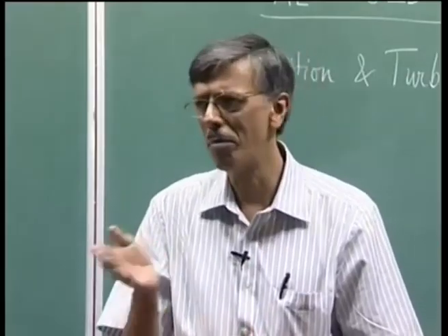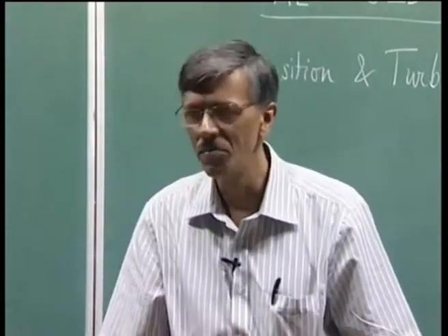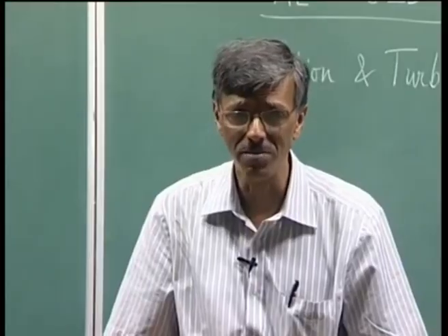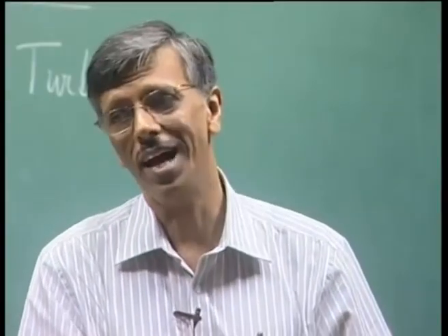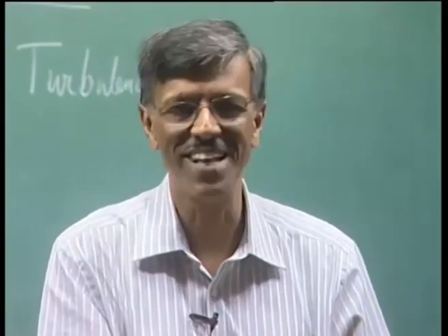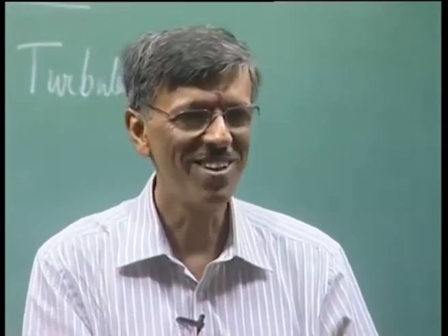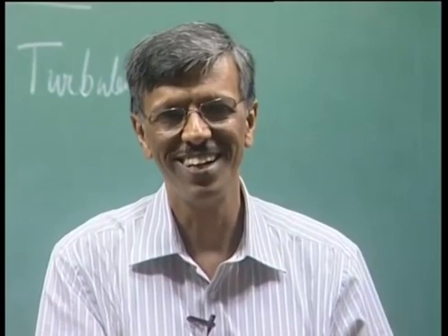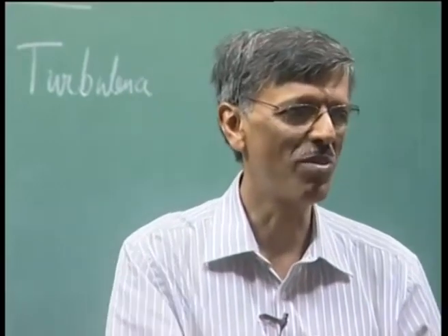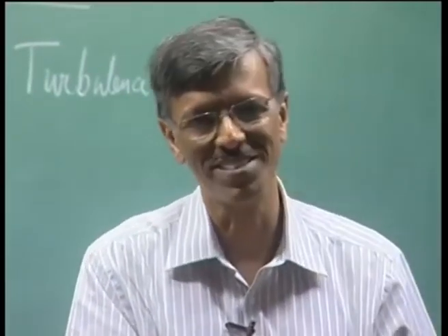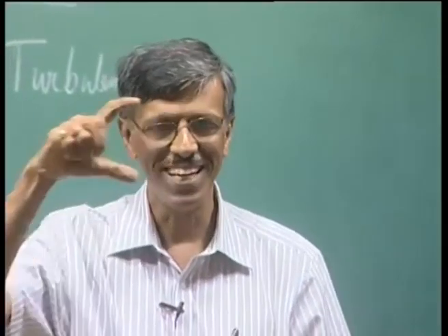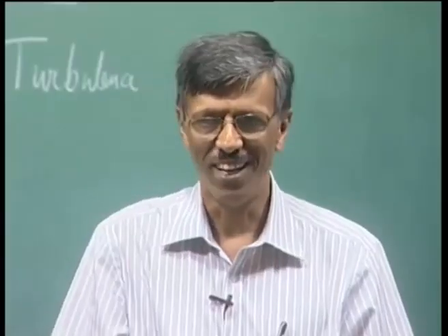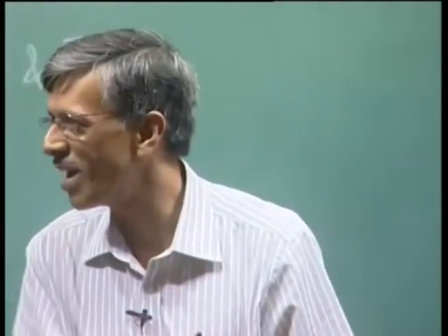While for a flow past a bluff body, we will show that the primary instability is a temporal instability, and nonlinearity here plays a very interesting role. Nonlinearity here actually moderates the primary instability. So, the waves keep growing, but then it saturates. Okay, we will spend a lot of time doing this.